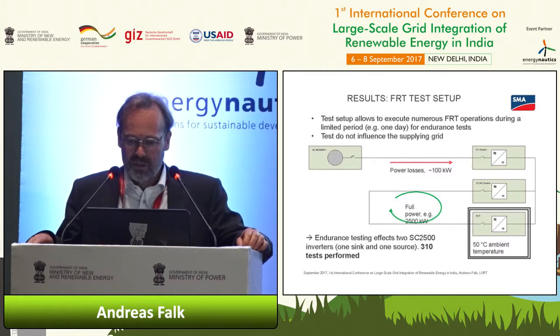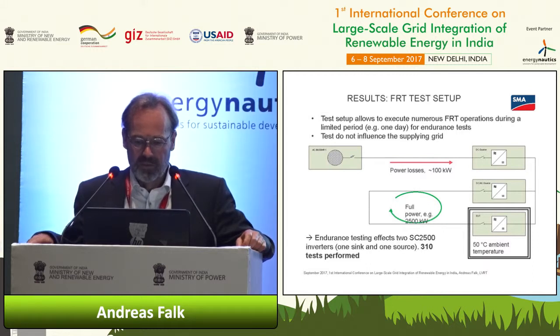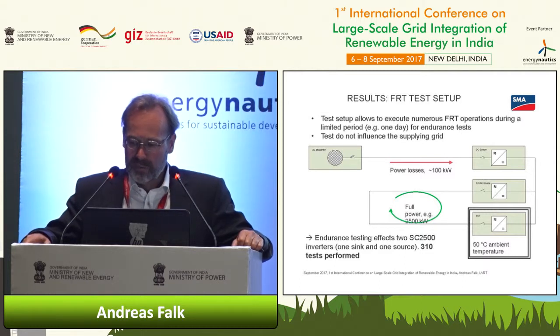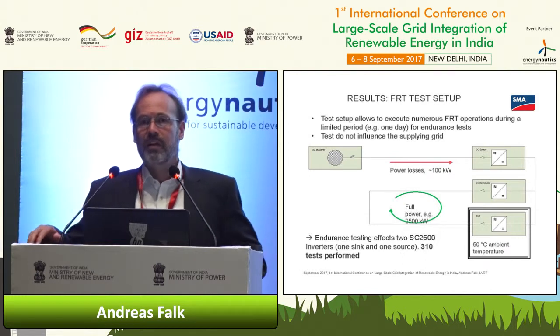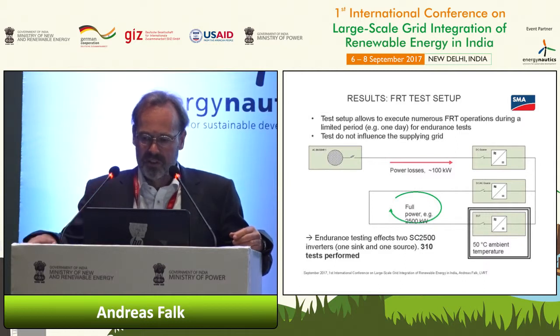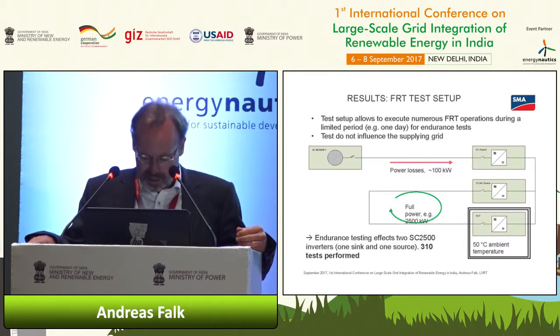What you should consider is, in case you have a voltage dip and you inject reactive power during the voltage dip, the voltage in the PV array will rise to no load voltage, because there is no burden left for the array, because the inverter is injecting only reactive power, not active power. And in that case, the voltage in the equipment in the array rises.